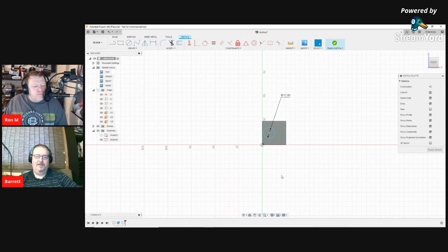So now to do the dimensions again, you're going to want to hit the D key because your dimension icon's gone away. There you go. Now you're going to click the center. And I was dimensioning to the origin. It's a cheat or a hack, but you can dimension to any one of the sides. Dimensioning straight to the origin, though, is okay. So I press in the center, and what do I do? And then press in the center of the origin. So if you hover over the origin at the X and the Y axes, that wonderful little black and white circular icon there in the center.